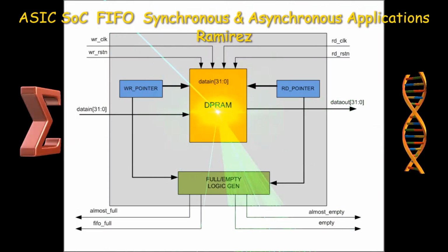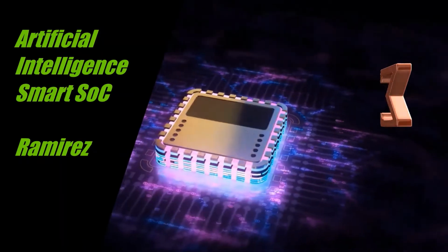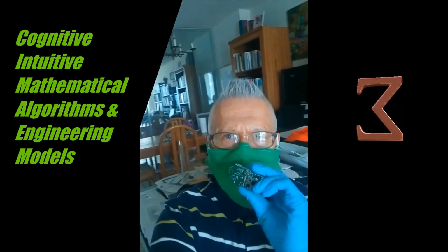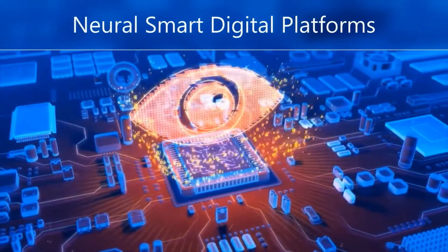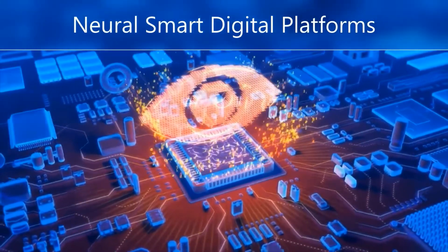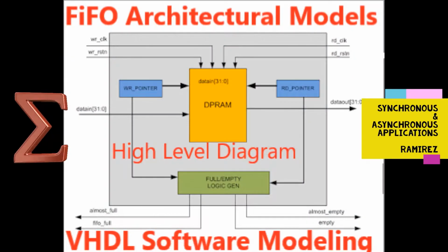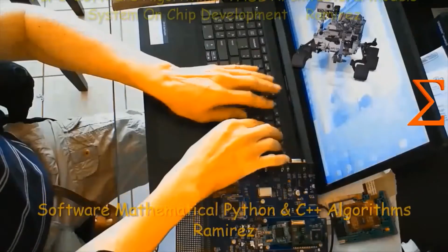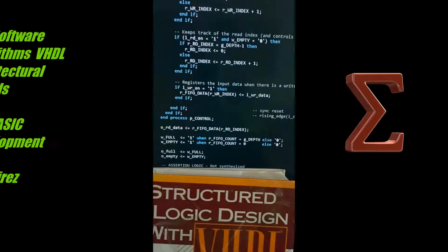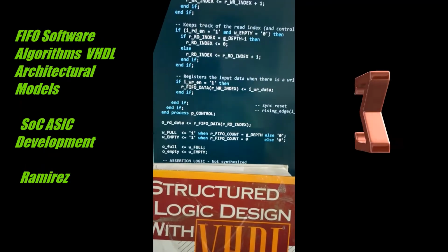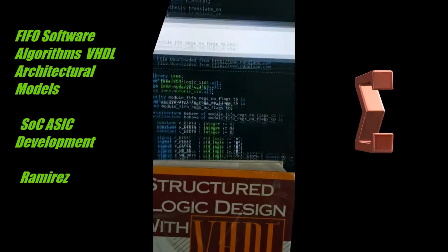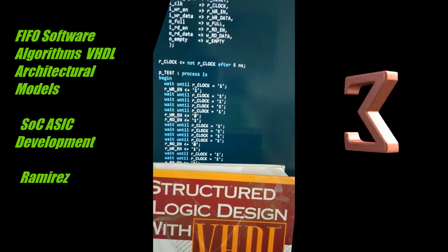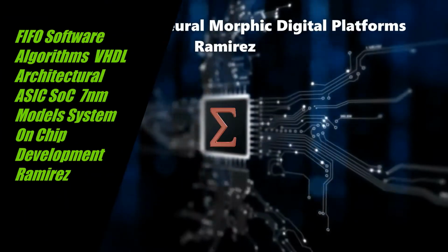Here in this project, as illustrated in this video, the FIFO partitioning with synchronized pointer comparisons is used for comparing and synchronizing the design working on two clocks, one for transmission and one for receiving, which uses gray counters for comparison of full and empty registers of RAM, which is the FIFO buffer for writing and reading the data values.